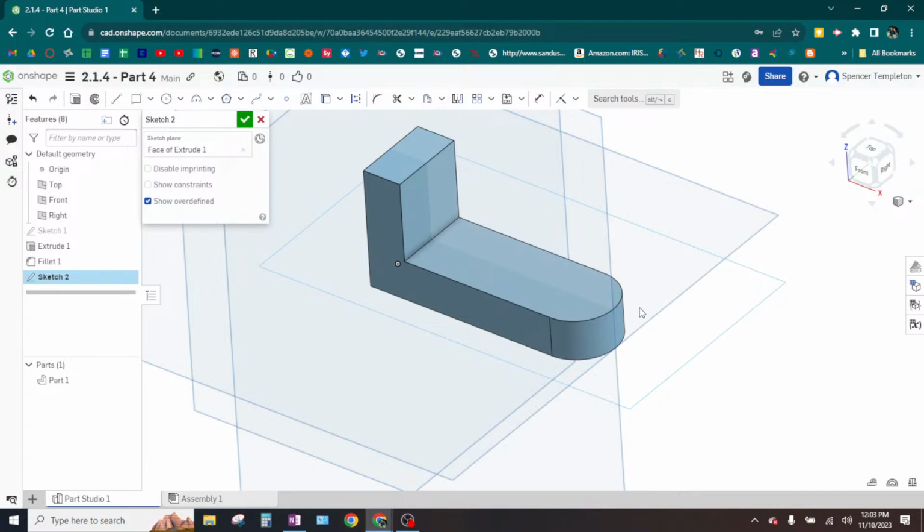And there's two ways you can do this. You can draw circles, or you can place points and use the hole feature. Since these are just circles, I'm just going to draw circles. Okay? Some of you may have seen that hole feature or whatever. That's like if you're trying to make holes where they're threaded, or you can have V-shaped countersinks or cylindrical countersinks, or for putting screws in and stuff. That's a little bit more complicated.